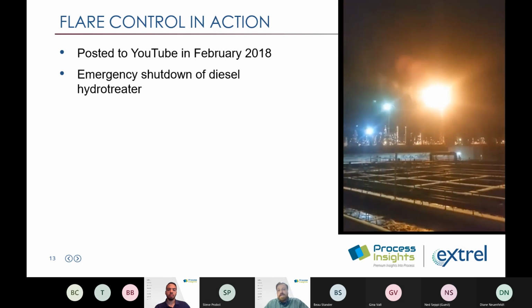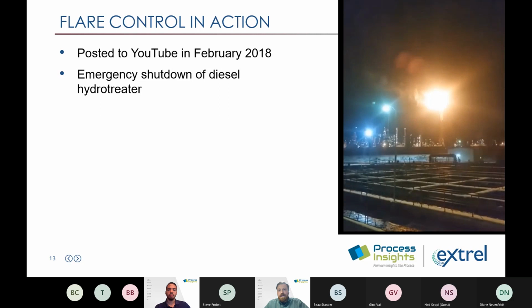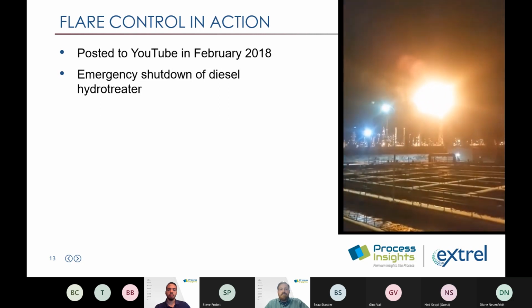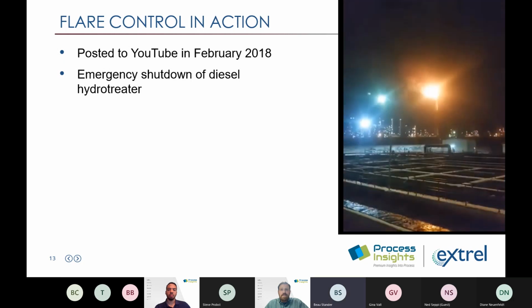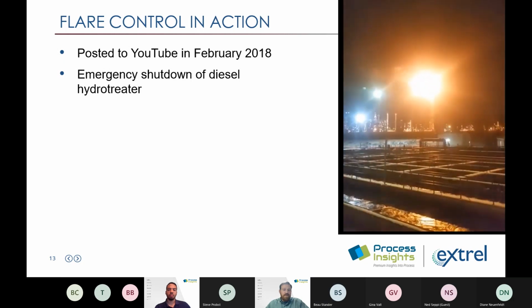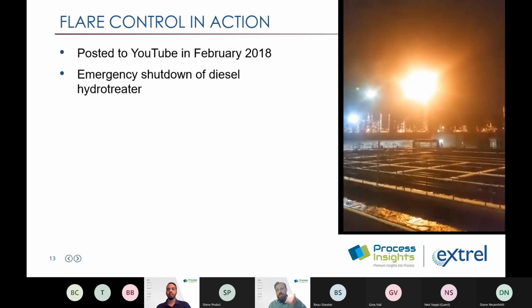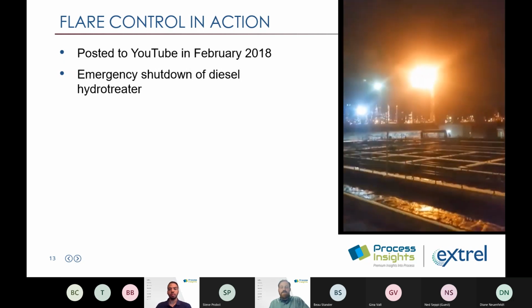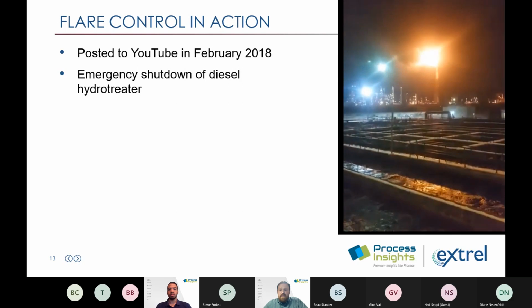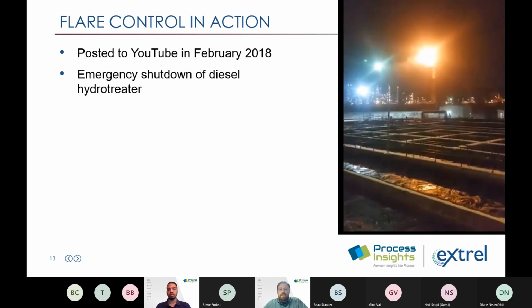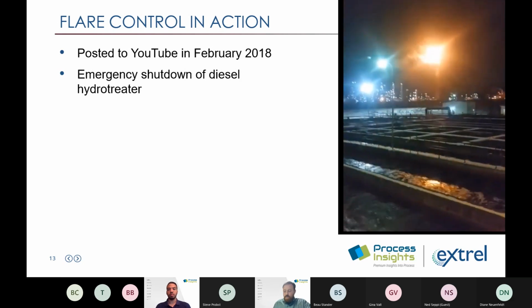And actually, in this case, when the EPA came knocking 2 days later, which they did, the site was able to sit down and demonstrate, here's what happened, here's what our flows were, here's what our vent gas heating value was. Our combustion efficiency never went below 98%, and this was a totally compliant event. So it worked out really well.